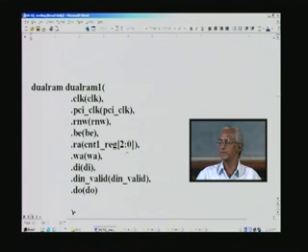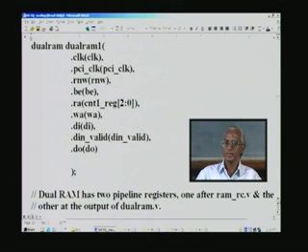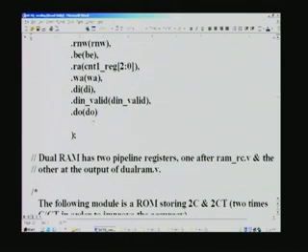And note that only the 3 LSBs are used for the X matrix, because in the first computation of Cx, we take a row of C and then take a column of the X matrix, and repeat the same for other columns of the X matrix. That means we advance to the next row of C only after processing 8 columns of X, and that is the reason why this is put as LSB, and the MSBs of the counter, that is bits 3, 4 and 5, will be for the C matrix, which we will be seeing later on, and the final output is D naught here, and this is applied to the second stage, which we will be covering shortly.